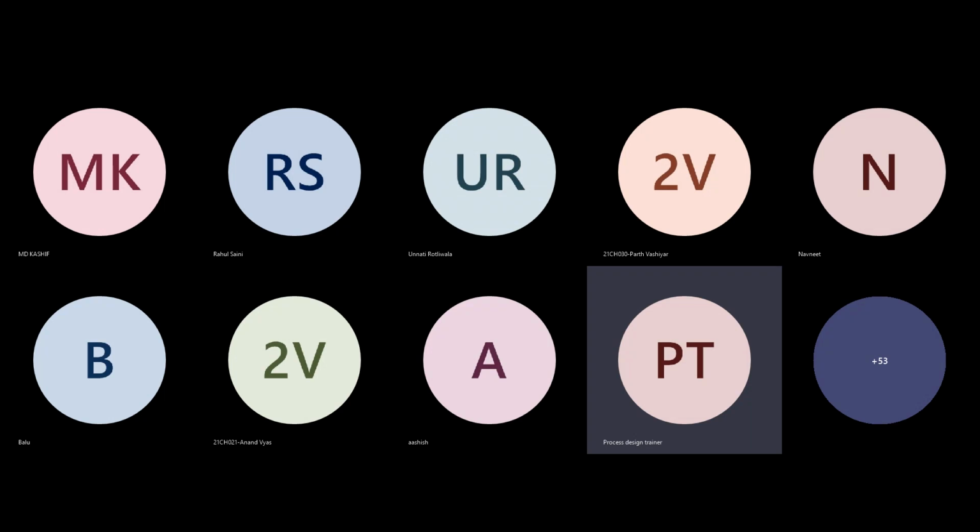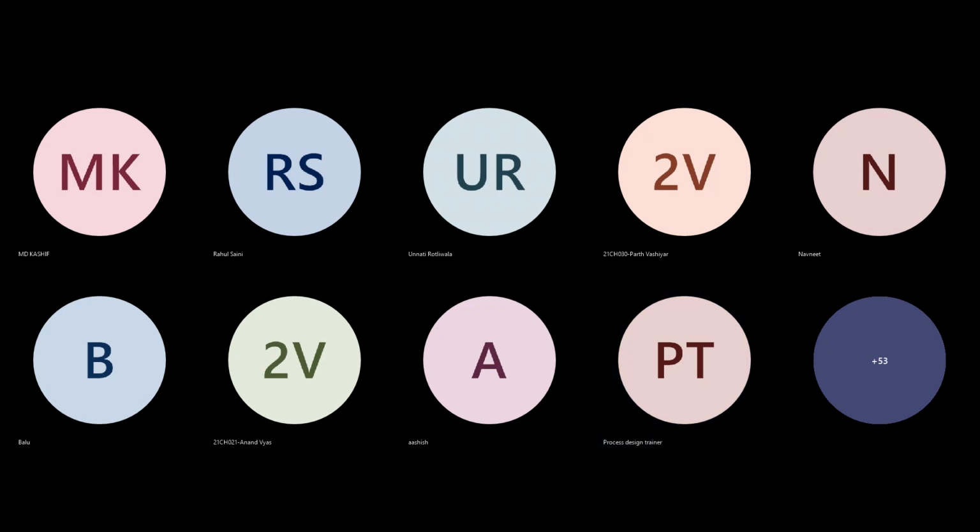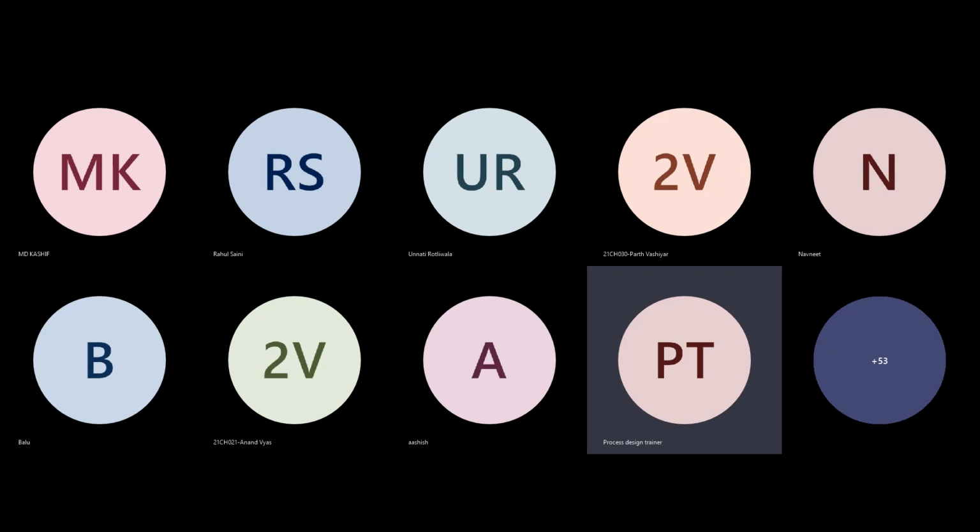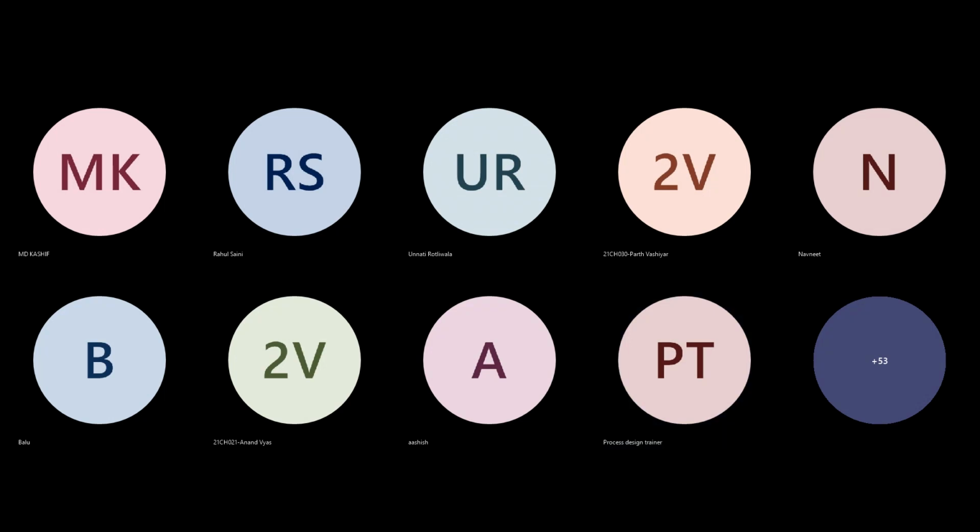Another possibility is you can reduce the temperature of the fluid. If you reduce the temperature of the fluid, then your vapor pressure will also reduce. Another possibility is to reduce the pipeline fittings or the suction line length, so that your pressure drop will be minimum. So these are the different criteria. And increase the size also, the suction size. Yeah, increase the pipeline size in the suction line also.